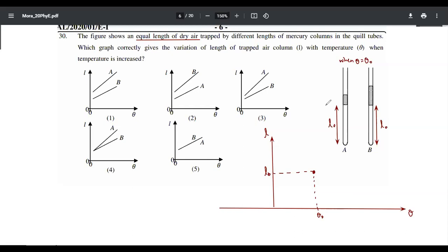But the problem with this question is, what is the pressure here? Here P naught. This height we will take as h1. This small height is h2. Now inside this pressure is P1. Inside this pressure is P2. Now we definitely know who is larger. P2 is larger, no, people. P2 is larger because you can write P1 equal to P naught plus h1 rho g.